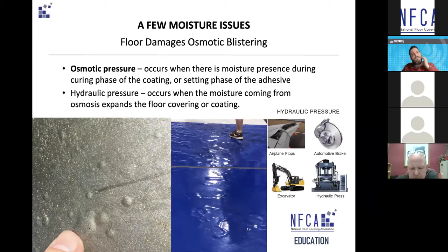Moisture problems can come from many variations of moisture. If there's alkali moisture, it can break down an adhesive. If there's just too much water under a floating floor, it can create smells. Osmotic blistering is a major cause of failure that we see, especially in coatings or epoxies, as you say. Can you describe osmotic? What is that? Yes, certainly. If people get this, it's helpful.